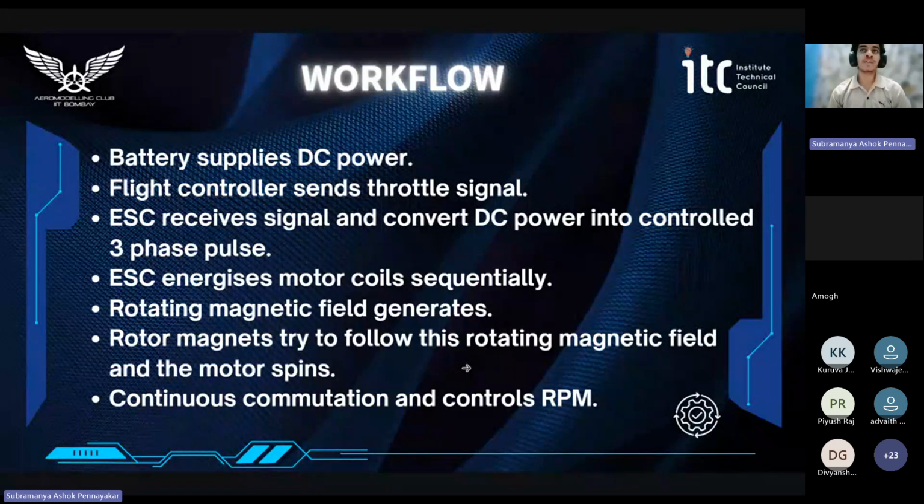You might encounter this term called duty cycle. Duty cycle explains how much current is being supplied to the motor windings. As pulse width modulation controls the torque and RPM, which I'll explain later in the motor section. Yes, so let's keep moving.